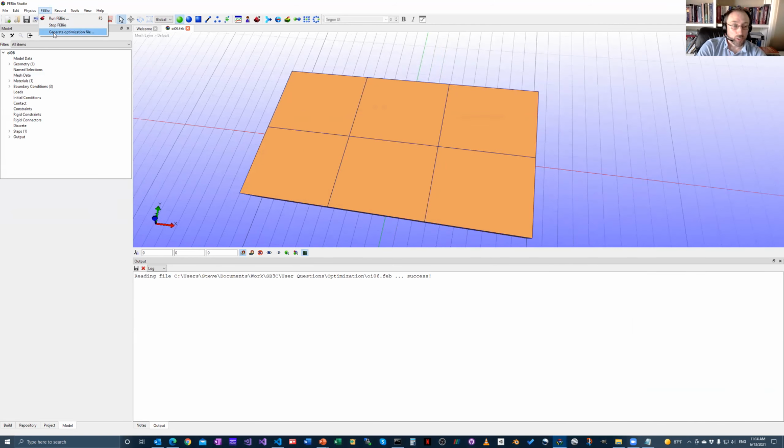You can then set the parameters that you want to optimize. In this case, I think it was just a Poisson's ratio, so specify initial values and a range. Then you can specify the objective parameter, which in this case was just UI, and then you can generate some points here based on a function, or you can just import them from the clipboard. So you can just copy and paste them, for instance, from an Excel spreadsheet. And then you would export that file.